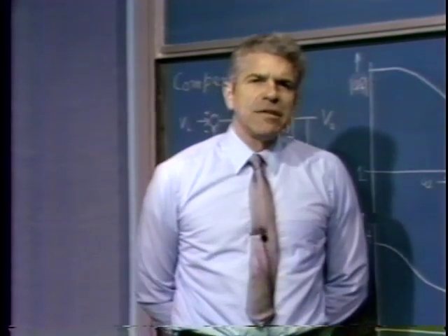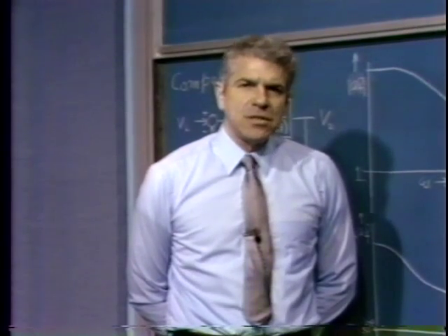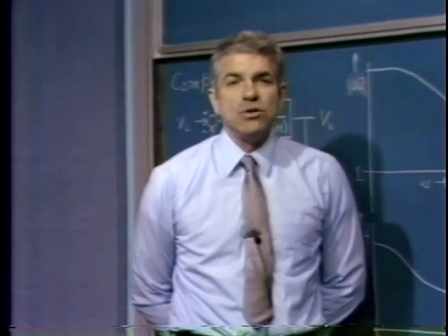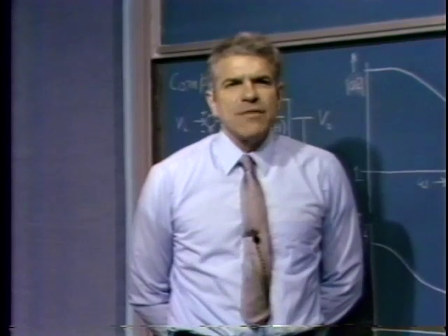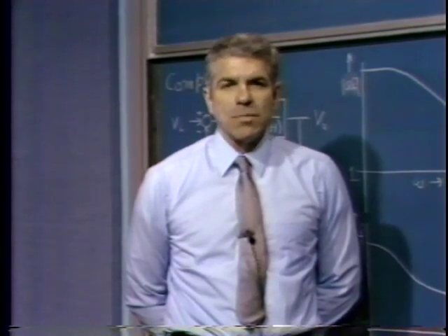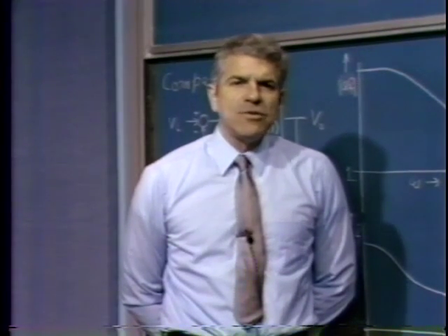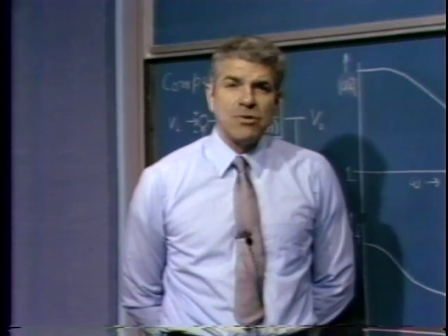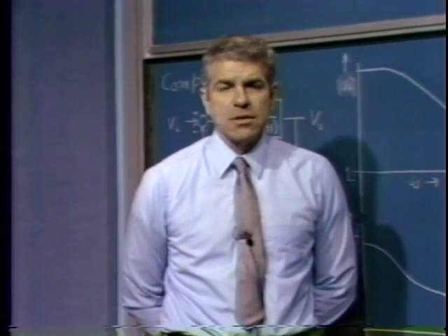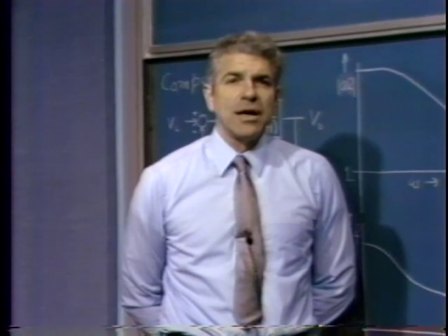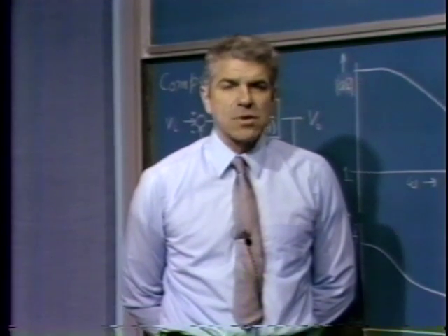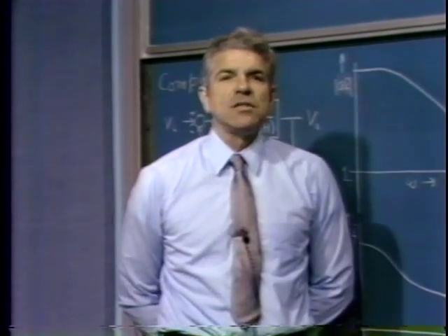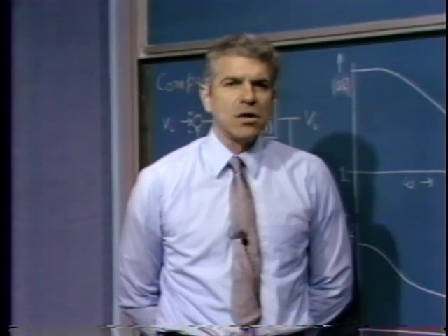Gain margin is kind of an override kind of a thing. Not much happens to deteriorate system performance until we get down to gain margins that become too small. And what's too small? Well, if you have a gain margin of 3 or more, possibly, or maybe a little bit more than that, it turns out that the gain margin has relatively little influence on the relative stability of the system. It does give you a measure of how much margin you have, how tolerant or intolerant you are to changes in various system parameters, how sensitive you are to changes in certain quantities that affect the loop transmission magnitude. For example, if we had a gain margin of 3, then increasing the loop transmission magnitude by a factor of 3 would cause the system to become unstable.